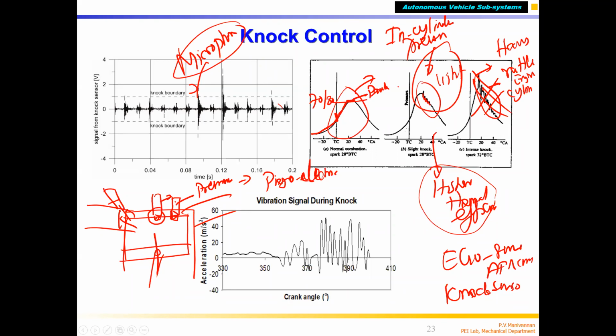That varies depending on the petrol or diesel engine, the compressor, the cylinder capacity, all those things. Okay, so you can measure. If there is no knocking condition, you will see a smooth pressure signal, correct? If there is light knocking, the pressure signal is not much different, because knocking happens here, correct? Then heavy knocking. The third procedure is using